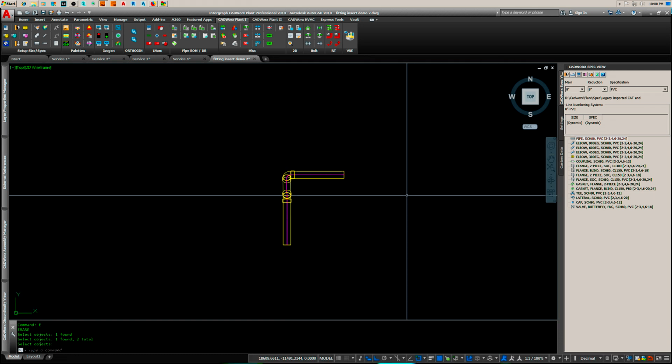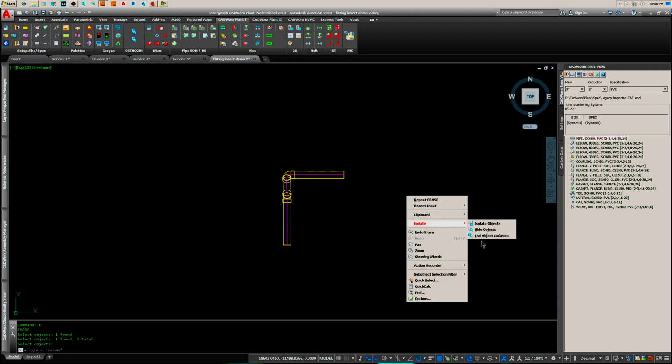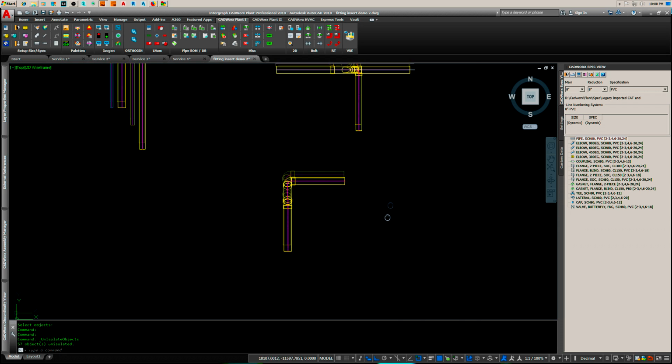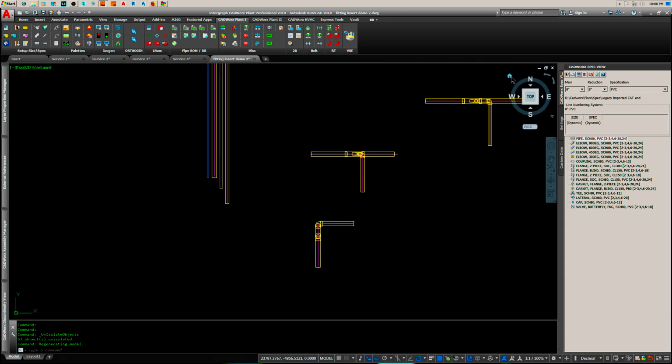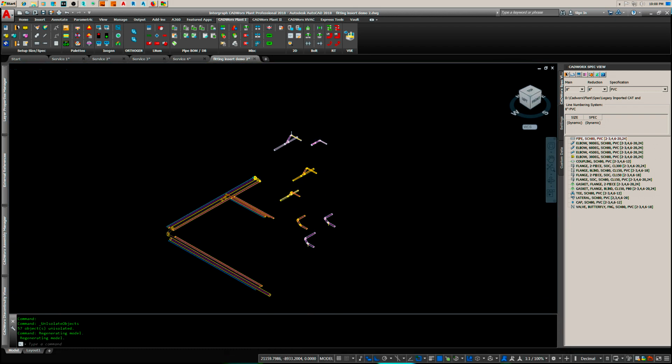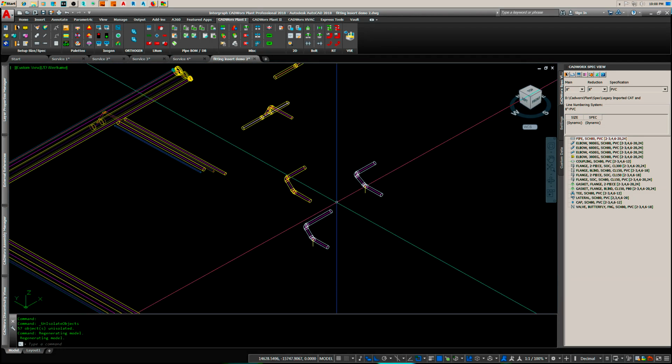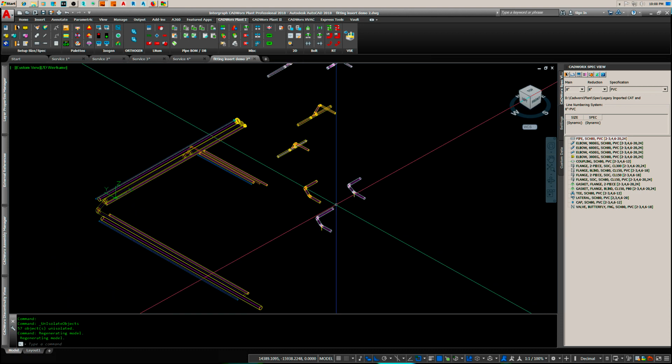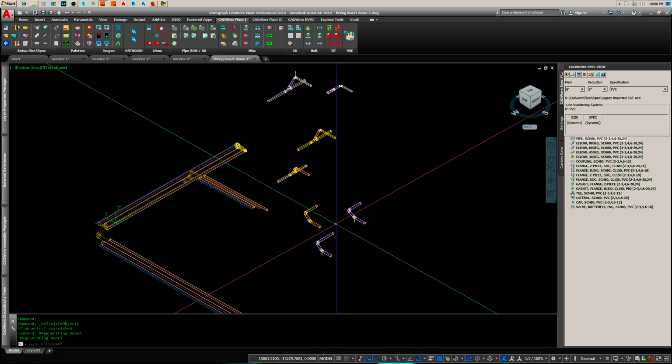And then we write block them out. When you write block it out, you want to set all of your blocks to layer 0, so that when you insert them and explode them, they take the inherent layer that you're currently on. And next I'll show you how to use them.